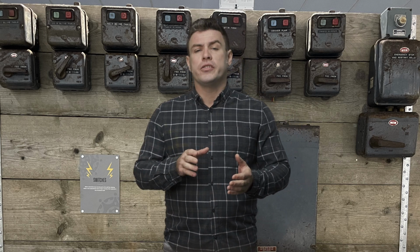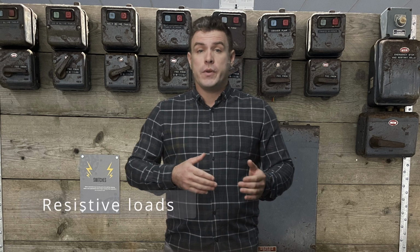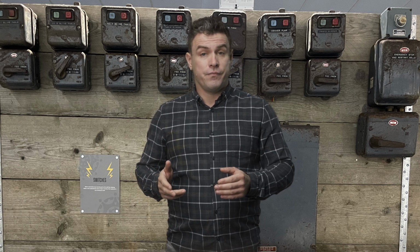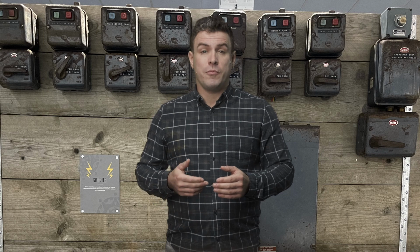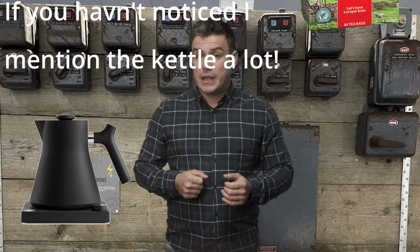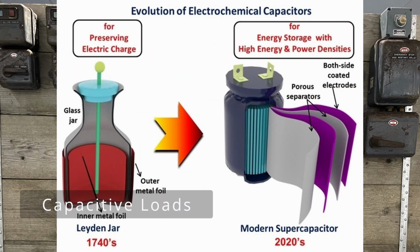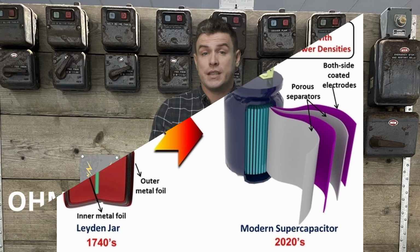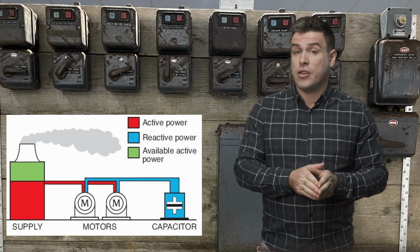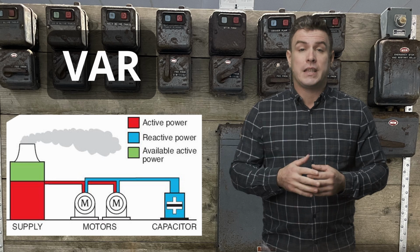Moving on to what I learned about with electrics this week. If we have a simple resistive circuit, we can measure the power by timesing the current squared by the resistance value. A simple resistive circuit could be a kettle. This would be referred to as active power. However, in a capacitive circuit, the capacitor charges and discharges as the voltage changes, meaning that the formula is no longer valid. We would measure this type of circuit as reactive power, and it's expressed as reactive voltamperes.